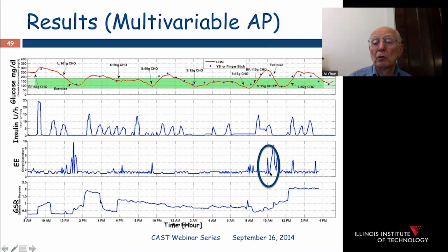And because of the energy expenditure signal, we are able to put together in the controller some additional logic that says that if that person is exercising, then go easy on the insulin infusion, so that while the glucose value is high enough over the range that we see as a desirable range, the amount of insulin that's being infused is dropped very quickly in order to prevent potential for hypoglycemia at a later stage.